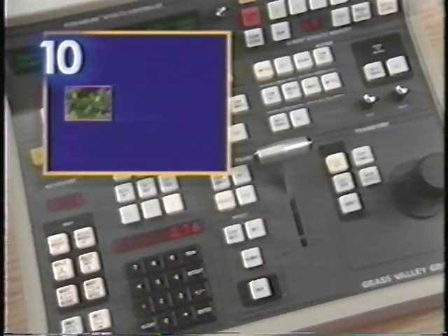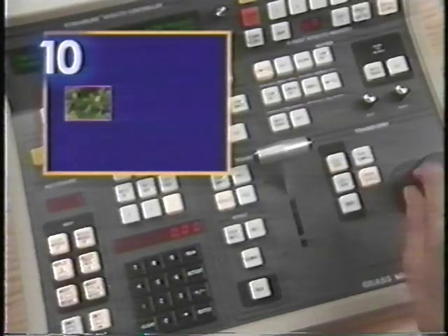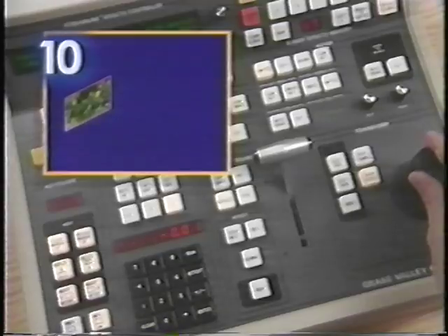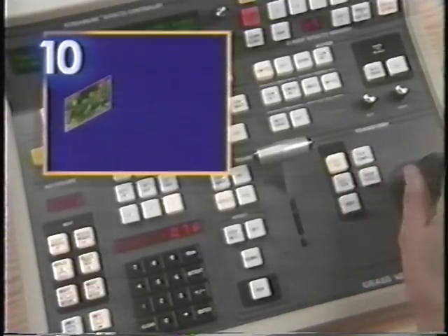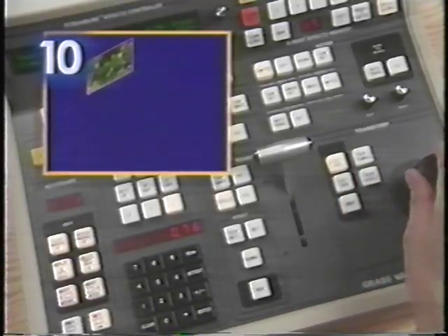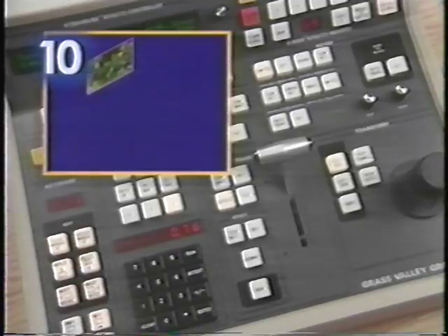For keyframe number 2, change the picture in the working keyframe buffer by skewing and relocating it using Skew Aspect and Locate Size. Now press Insert After. This will insert the working keyframe into the current effect space as keyframe number 2.